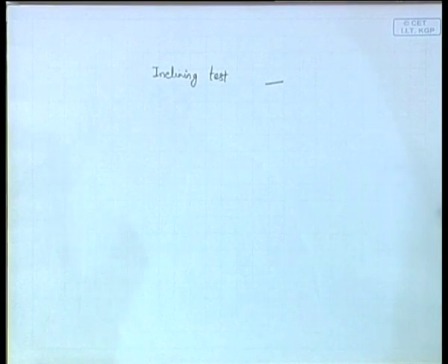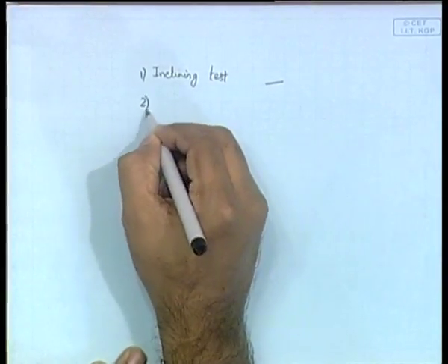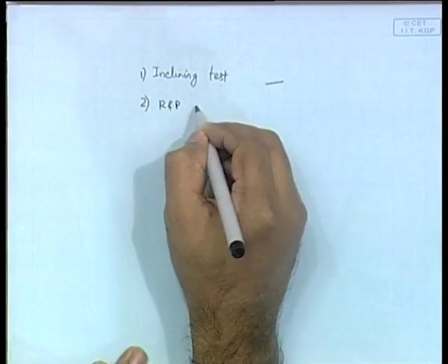So first of all you develop the hull. Once that hull is developed, you need to do stability calculations, means you need to make sure that the stability of the ship is all right for that particular hull. So there are a couple of experiments. Two important experiments that are conducted are, one is this inclining test, and the next one is actually the resistance and propulsion experiments.